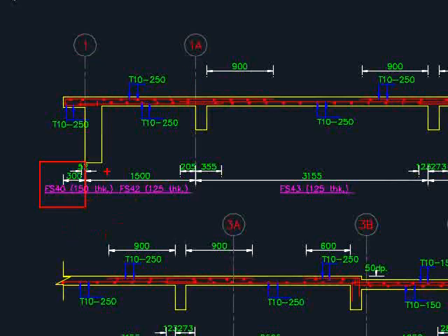There will be the names of the floor slab as well as its thickness. The thickness here is 150. It is due to the requirement of the architectural fixtures, which you can measure from the cross sections of the building as given by the architect.